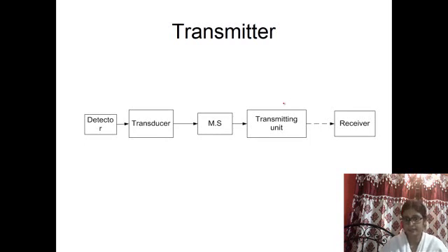take the corrective action. Accordingly, the control action will be sent to the final control element to adjust the energy input to the process. That is the fundamentals of the process control loop in feedback process, since mostly the control loops are feedback control systems.